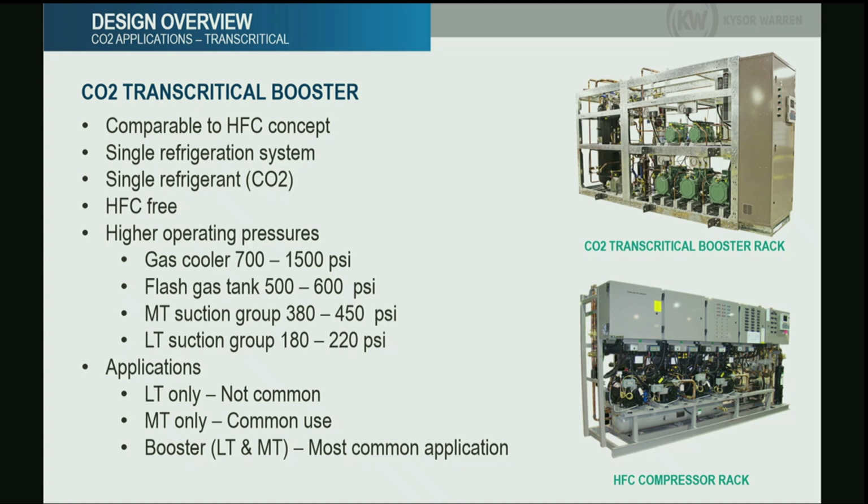Now, the CO2 systems can have about the same applications that we have with HFC. They can be a split suction temperature, when you have your medium temperature and low temperature, can be medium temperature only, or can be low temperature only as well. I do not recommend much the low temperature only, and I haven't seen many applications like that in the US. I have seen some in Europe, but not here. The problem with the low temperature only is that normally you will also require medium temperature compressors as well. So it's better to have them both combined, medium and low temperature.